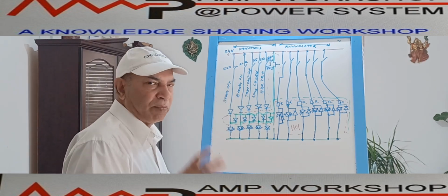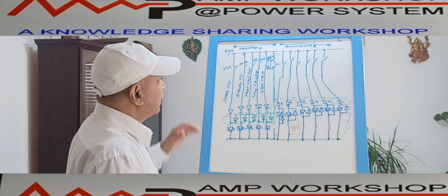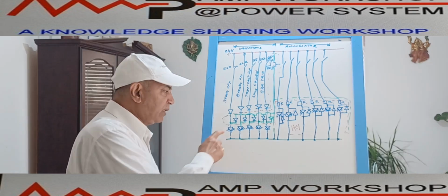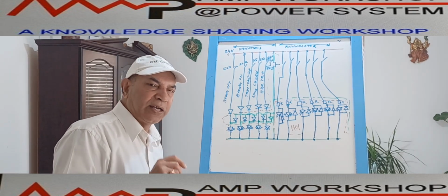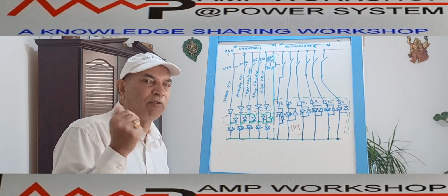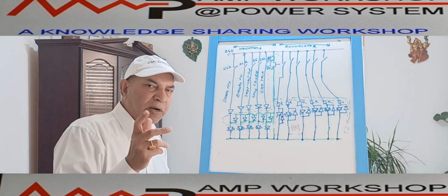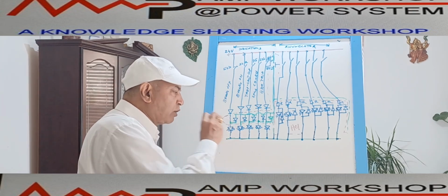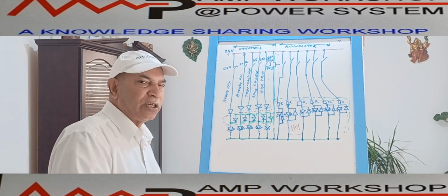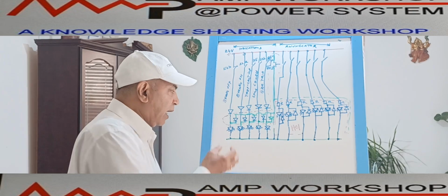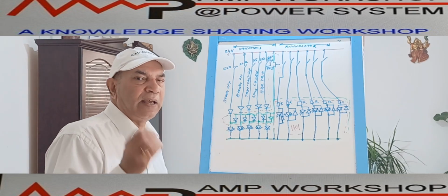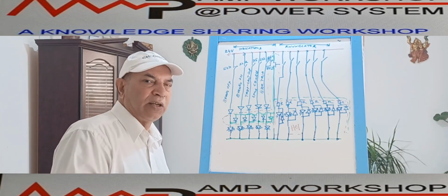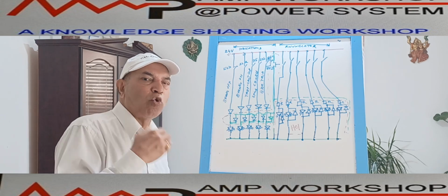Let's discuss how the first signal is working. In the case of the indication lamp, because it is a solid state device, these LEDs normally can take from 1.3 volt to 3 volt. That is the normal voltage withstand capacity of the LEDs. So you cannot apply a high voltage to the LEDs, otherwise the LED will burn itself. The LED intensity depends on the amount of current flowing through the LED. So these LEDs are very sensitive to over voltage as well as over current.